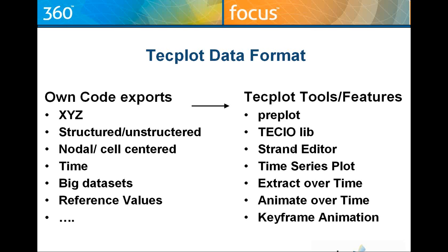These are, for example, constants or variables which indicate what you would like to use for velocity variables, for example, for the Tecplot analyzer. And you can use this additional input in order to give information about the data set created in the solver to Tecplot. For example, put some texts on it, like what kind of computation it was, which solver you used, what time and date the data set was created, and so on. We will see this later on.